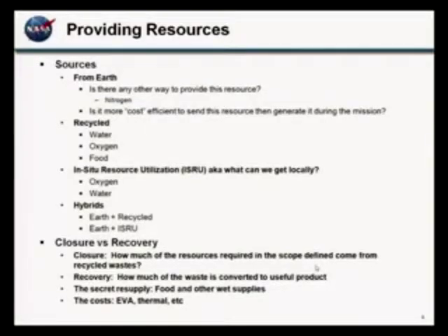No amount of larger radiator is going to fix it. So they need to use water evaporation during those hot phases. Mars, conveniently, is somewhat more moderated than the moon. The hots aren't as hot and the colds aren't as cold. So you may not have that issue, but you may look into it for contingencies and things like that.